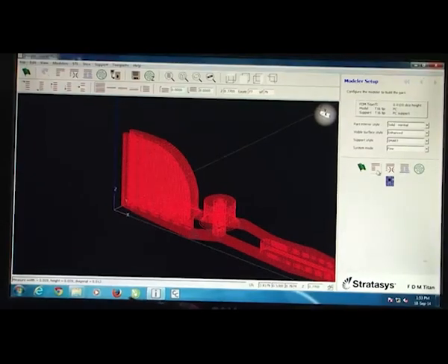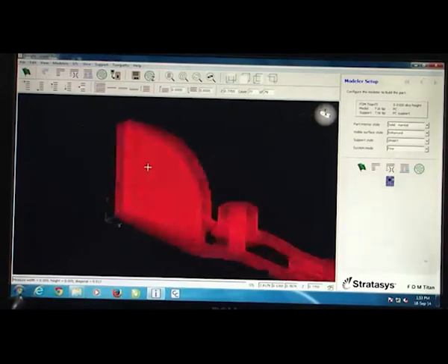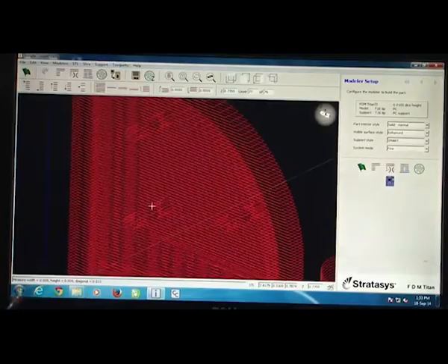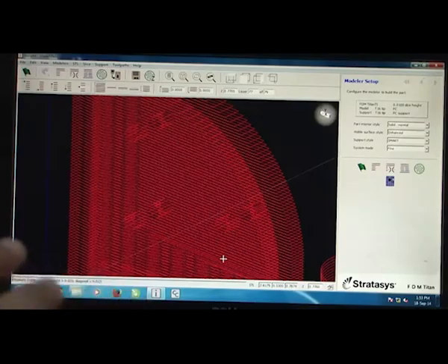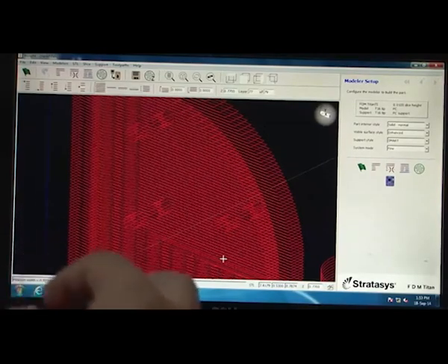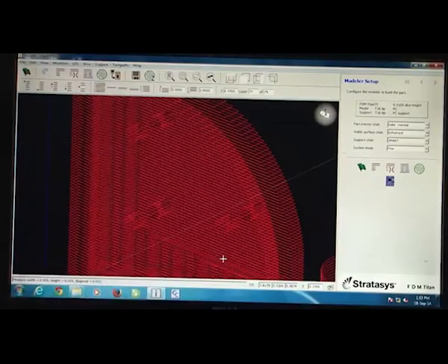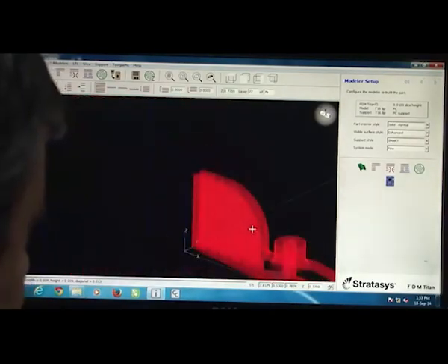So the other option now we have, once we have actually done the slicing, we have to create a support system here. There are certain holes, etc., which you are not able to see because of the intense slicing, but you can see there are certain holes, etc., which have to be created. Okay. And therefore there has to be a support within them, where typically the density would vary, etc., and there can be easy cleavage. Okay, so that the support can be later on taken off to create that hole in that particular dense structure.